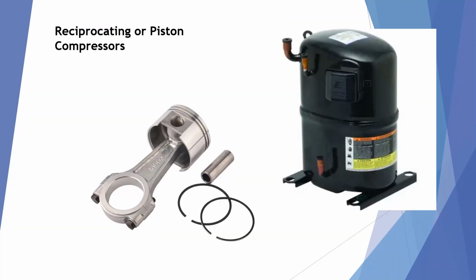You don't see too many reciprocating or piston compressors anymore, but when they were popular, the pistons on the reciprocating compressors were usually a lot beefier on heat pump models to endure the conditions that they would endure in a heat pump operation. Also, the reed valves on piston compressors were always susceptible to damage by liquid refrigerant slugging.